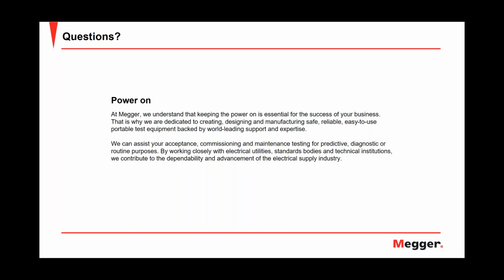So the first question is going to be for Henning. Where is oil coming from in the paper insulated cable? Okay, well, when you have what we call paper cable, the paper is not really an insulation medium. It's the oil that the paper is impregnated with that provides the insulation characteristic, dielectrics. The paper is only there to keep the oil in place.